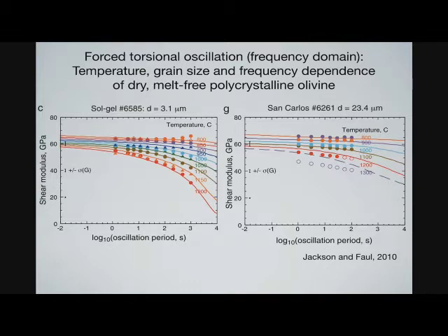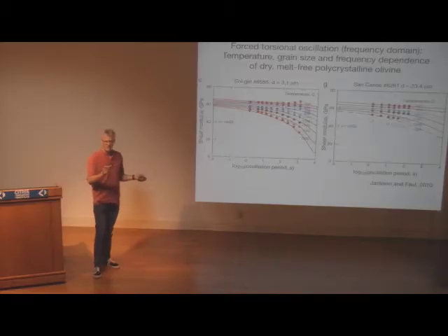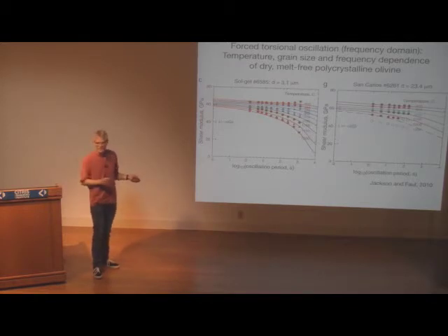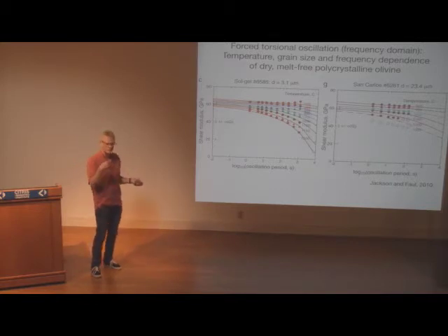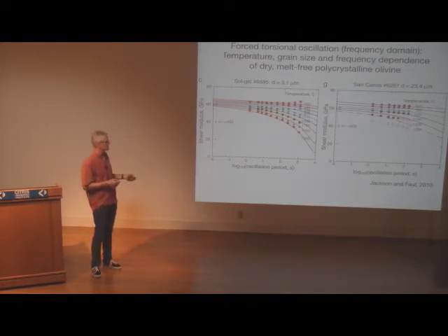At the coldest temperatures, most of it is just spring, it's elastic behavior. As temperature increases, it becomes anelastic behavior because that anelastic element becomes more and more important. And that also is consistent with the dependence on frequency. So the longer your period, the further you can push the spoon into the honey, so the more lossy the material becomes, the lower the shear modulus.